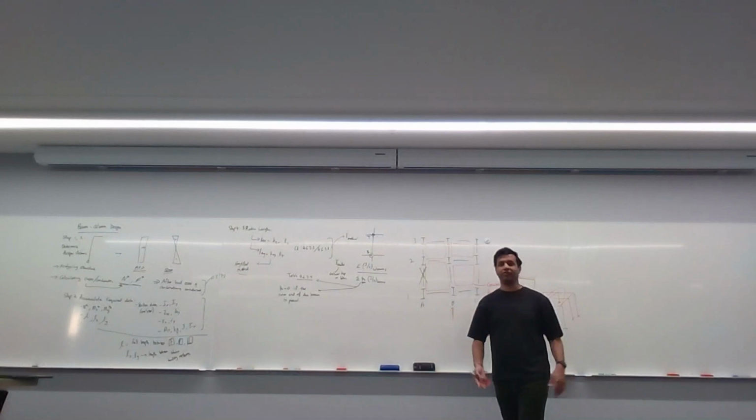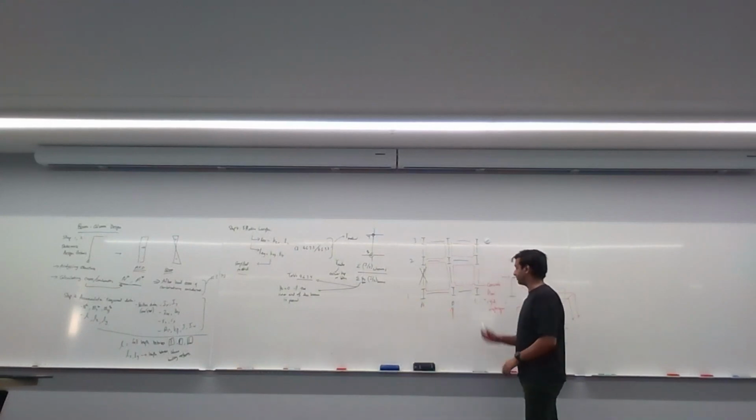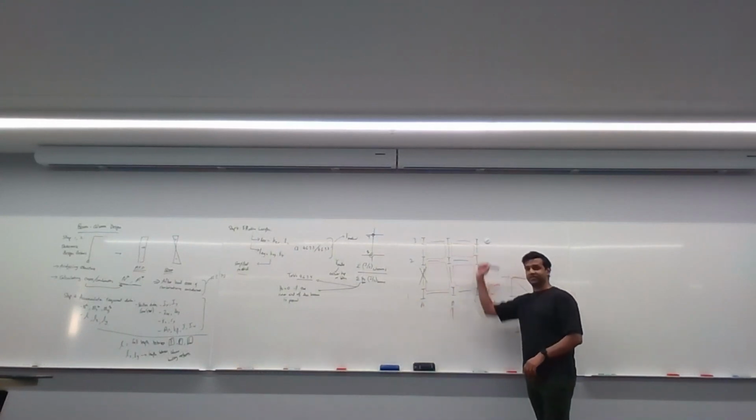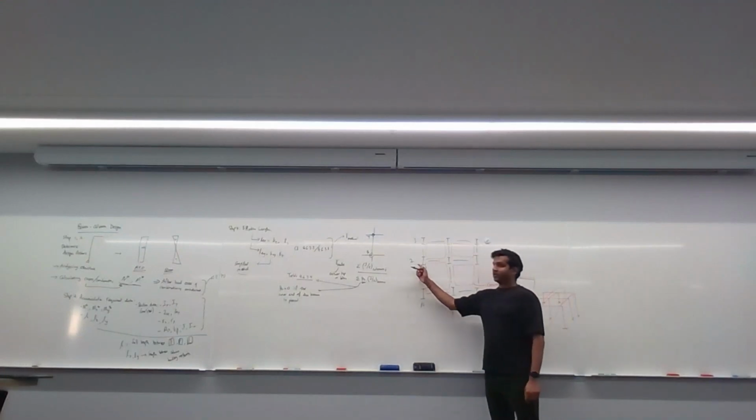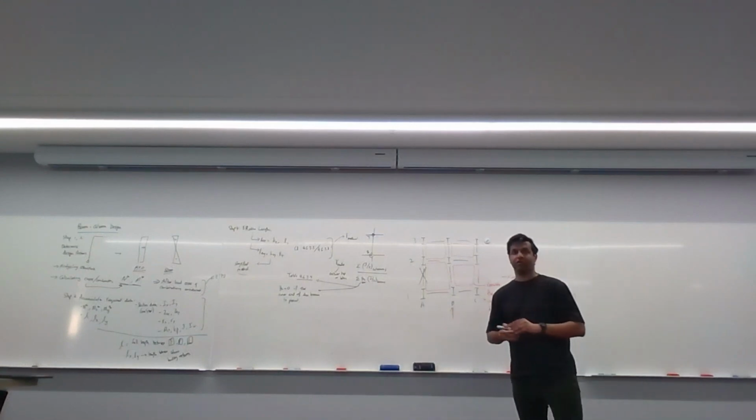Because usually when we design a floor, we're designing it for gravity loads, upwards and downwards. But if the floor is going to resist loads shooting across it, that's diaphragm action. If it's a rigid diaphragm, they are all braced. Everything is braced. But remember, if this is a concrete floor, is frame 2 braced or swayed?